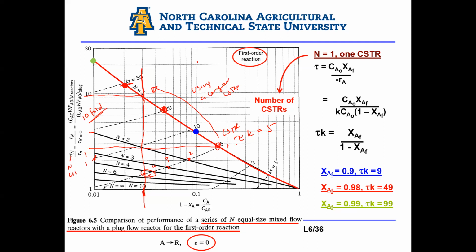So instead of using a much larger CSTR, I'm going to just use 5 smaller CSTRs with the same overall volume. Theoretically or mathematically, you're breaking it down into 5 smaller CSTRs. Practically, you're buying 5 smaller vessels.